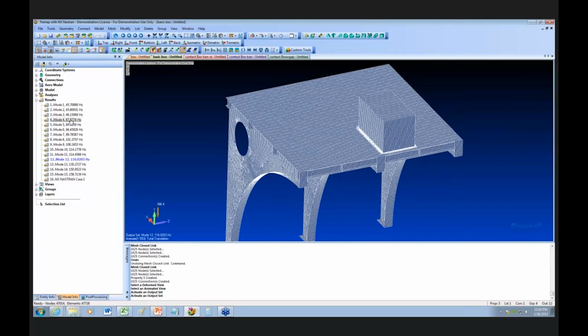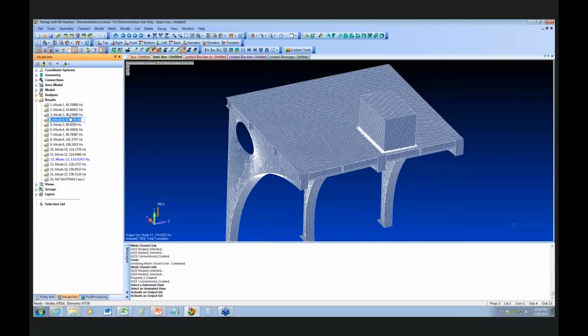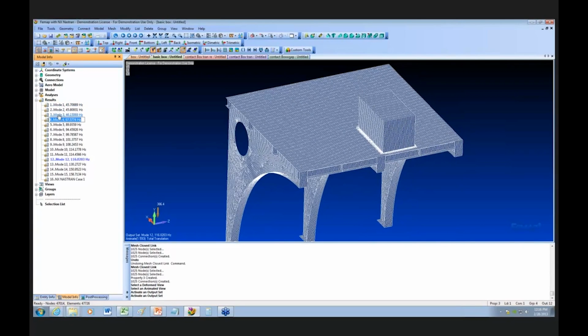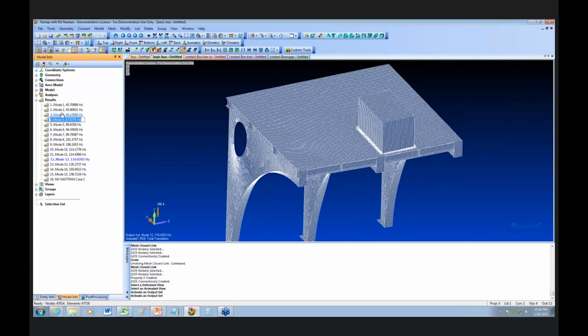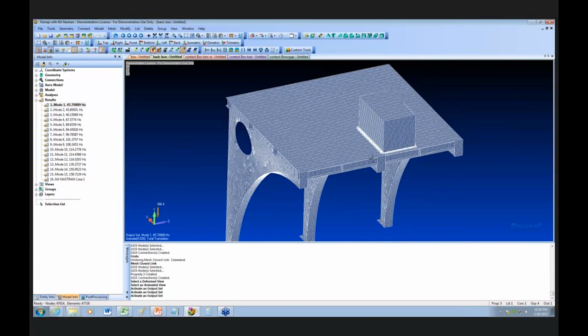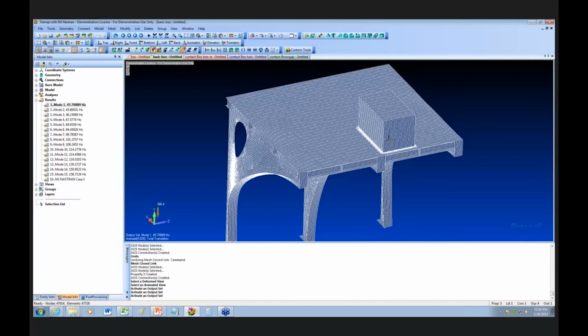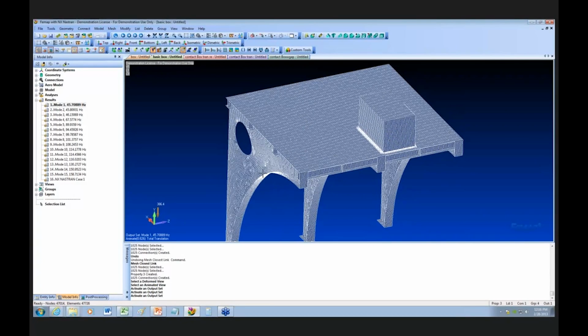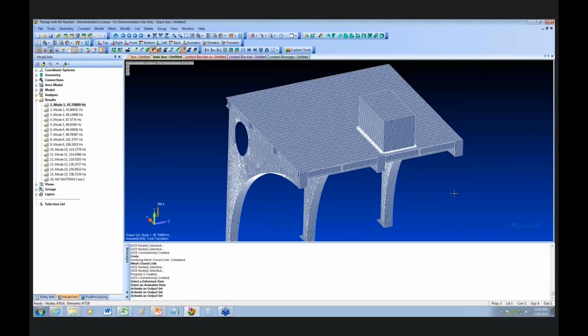The next thing, for damping purposes, is I want to find where the energy is going into the structure when it makes contact. This is the dynamic characteristics of the structure, the eigenvalues. I start going through this, and you have to use engineering judgment here. When this box strikes this frame, is the energy going to go into this mode shape? Probably not.